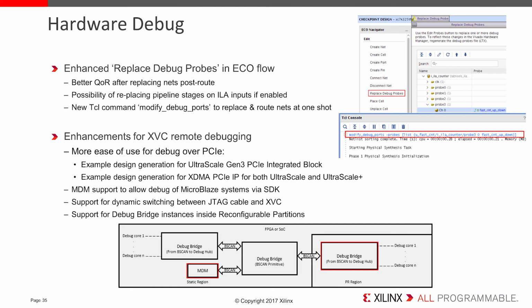Additionally, there are a number of enhancements to the XVC solution for remote debugging. In particular, there is now additional support for example design generation for debug over PCIe. XDMA PCIe IP can now generate its example design with the XVC feature for both UltraScale and UltraScale Plus devices.